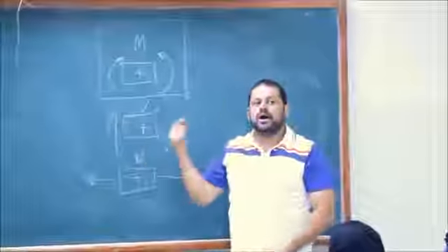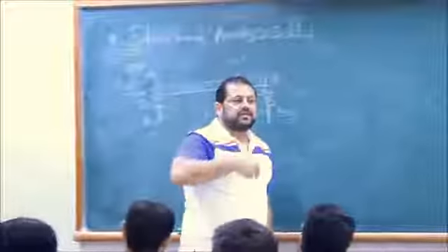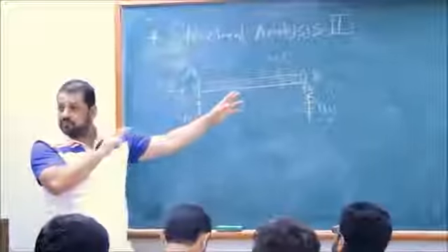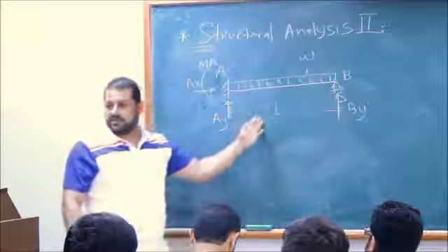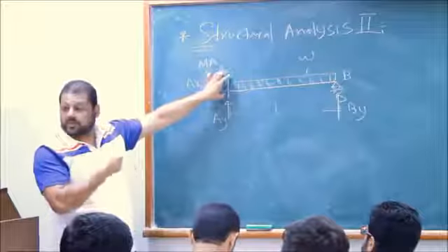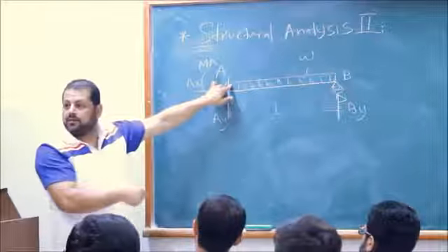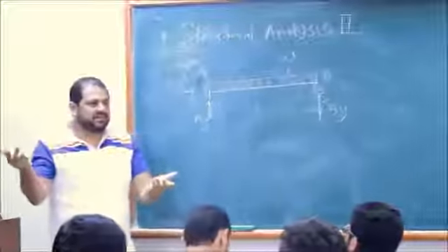Why? Because they have the ability for redistribution of stresses or loads. If one place gives up and reaches its ultimate, there will be a redistribution of load or stress. If yielding happens at this joint, it changes from fixed to pin and stays stable. You get a semi-supported case. But what's the disadvantage?